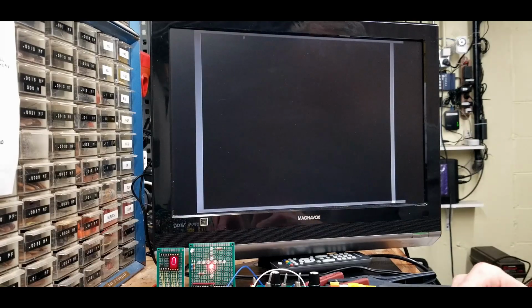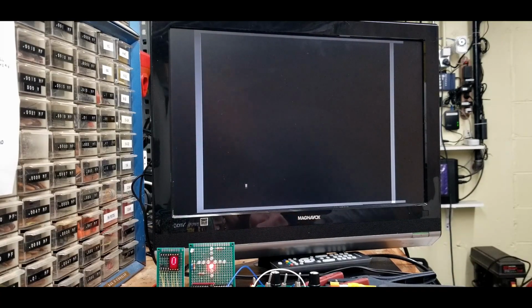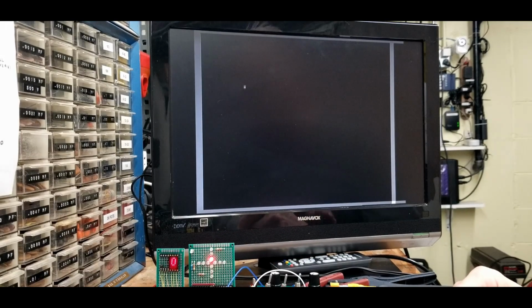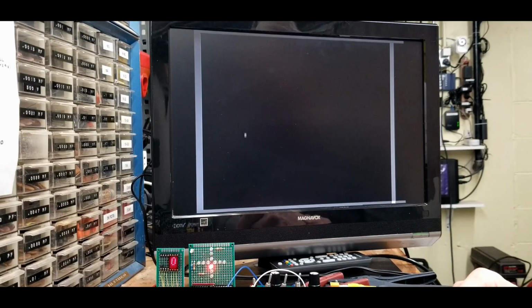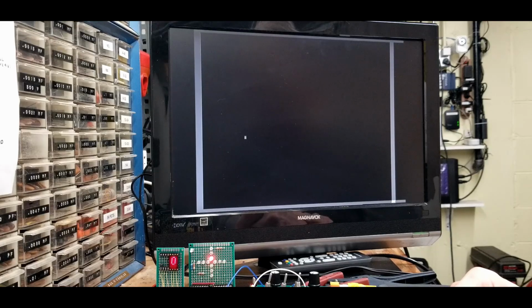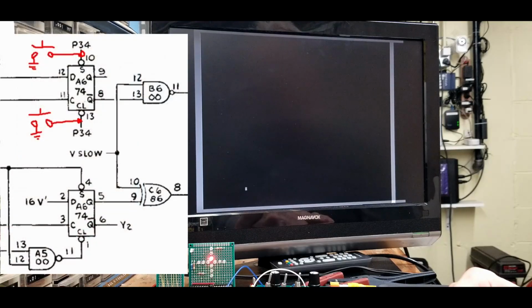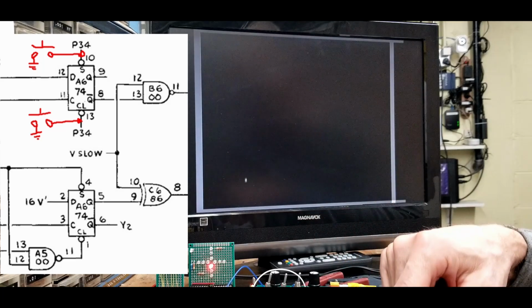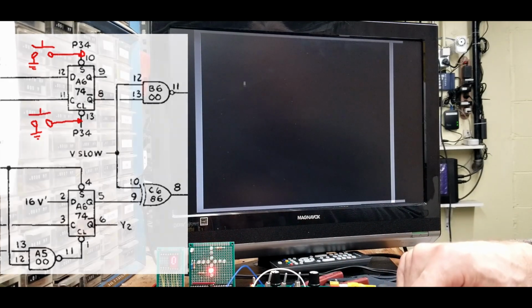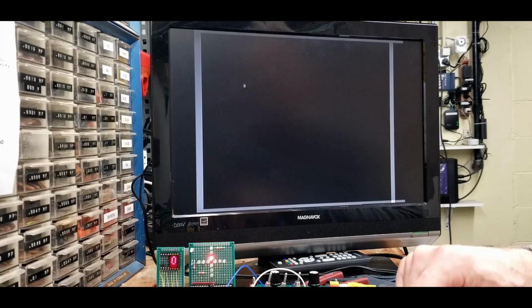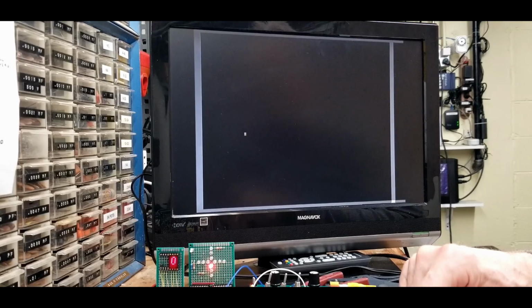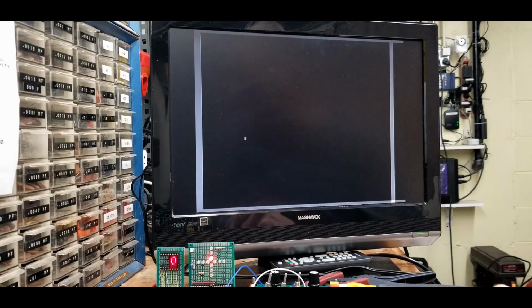Let's check out our Y motion work. I hooked up the Y-axis LEDs on our meatball display and froze X motion so we can test the basic direction changes first. Testing here is a little challenging since we're not hitting the paddle yet, but we can manually change a few things. I've already set the top latch, giving us slow speed, and resetting the latch gives us medium. We can toggle between those as if we hit the paddle center and outer edges. If you look closely, you can see that the ball goes through the left side and hits V-sync before changing direction, and it's brighter where they merge, as predicted.